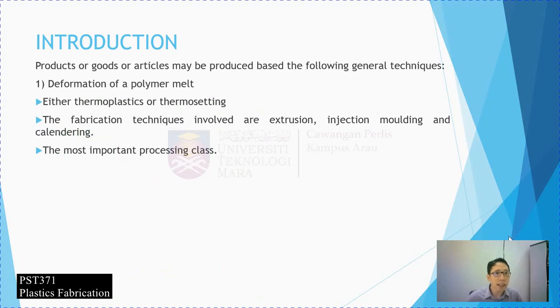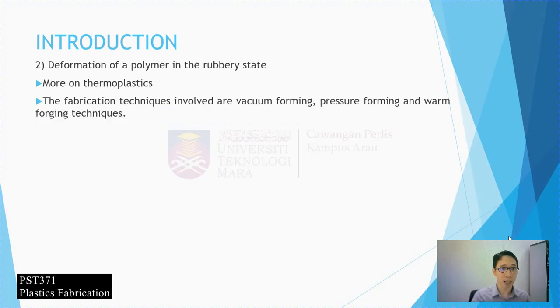The first one is, okay, product or goods article may be produced based on the following general techniques. The first one, deformation of polymer melts, either thermoplastic or thermosetting. The fabrication techniques involve extrusion, injection molding, and calendering. The most important processing class.